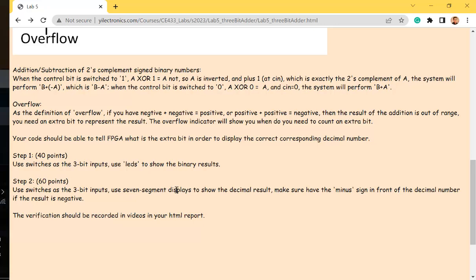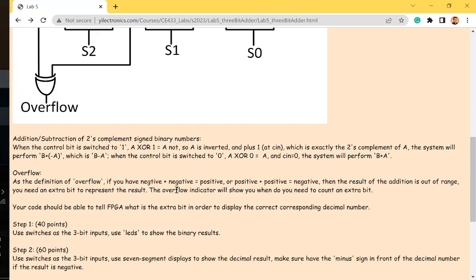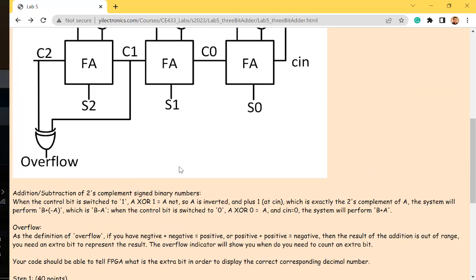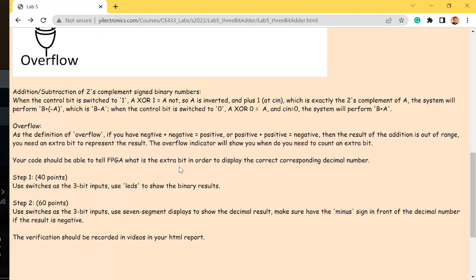Whenever you have this data as a 3-bit, 4-bit actually, if you have this 4-bit binary result, like a switch case, right? In this case, you throw these data lines to the 7-segment display to show this number. You're telling the FPGA to show what in there. You know what I mean? Okay, so you need a lookup table.